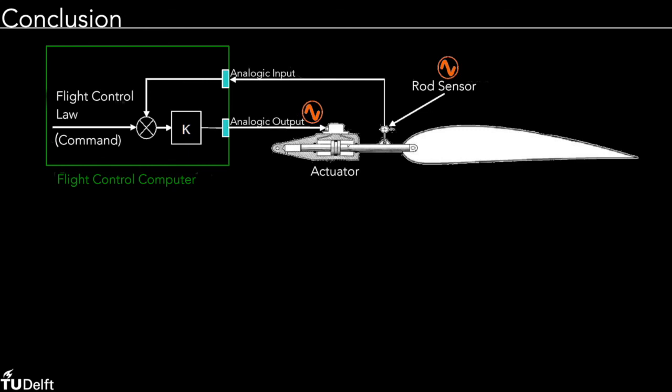In conclusion, we have considered the oscillatory fault case on an aircraft elevator servo, and we have designed a novel sliding mode observer based method for fault detection, which is fast enough to detect all the considered faults. This speed up of detection has been achieved by circumventing the filter that was needed to get the residual in previous work.